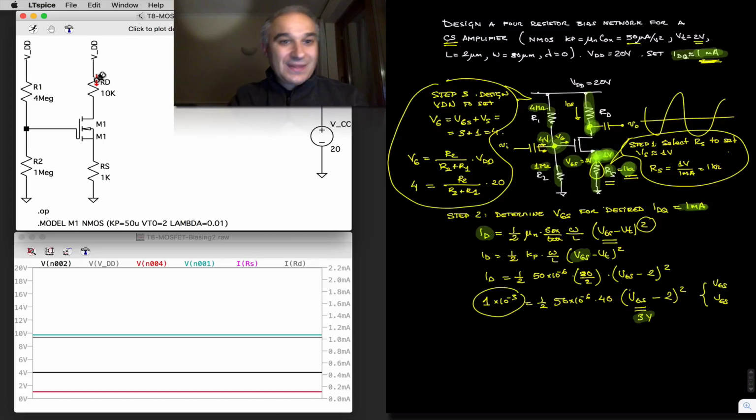That is the gain stage with MOSFETs, which is equivalent to the common emitter amplifier for BJT technology. But in this case, we can see that even in the discrete case, we can increase the input impedance in the network because we don't have to worry about the impedance looking into the input of the transistor, which in this case is infinity, as opposed to the case of the BJT, that will be beta times RE, finite. Thank you.